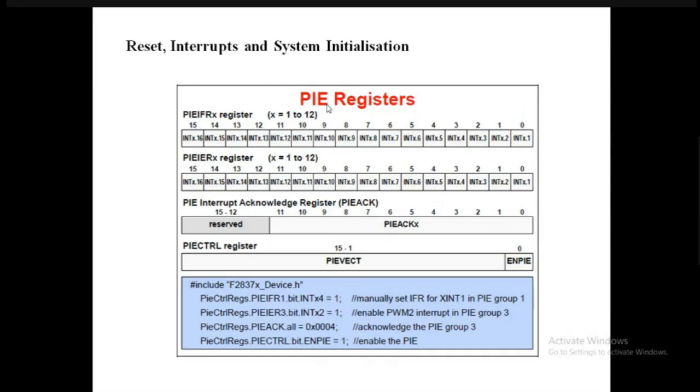You can say that, or another example you can take into account, is that if a certain dog is coming to your house and you're feeding him every day at the same time. So it's kind of like that: your clock will be serving the interrupt, and whenever the interrupt is calling, that particular ISR will be executing that loop. And the ISR loop is responsible for writing or executing any code. So whatever you are writing in the ISR loop, okay, that will be one particular separate function, and it will be running your algorithm along with your main loop.